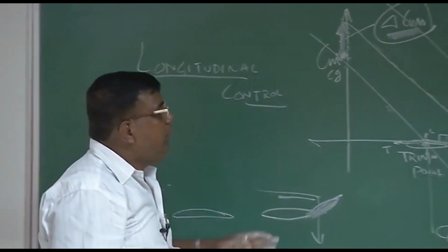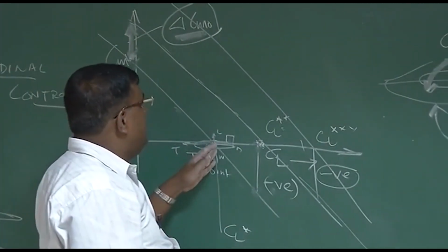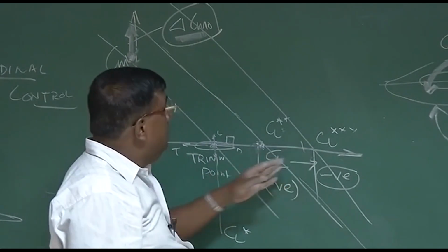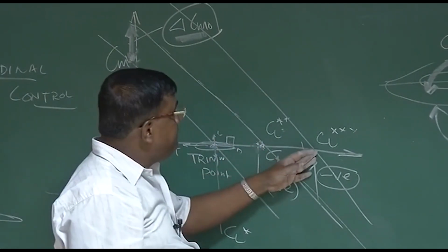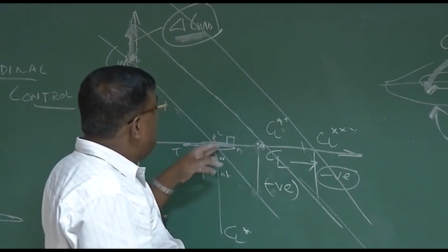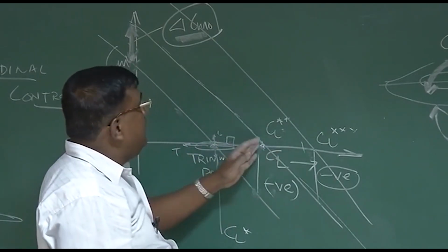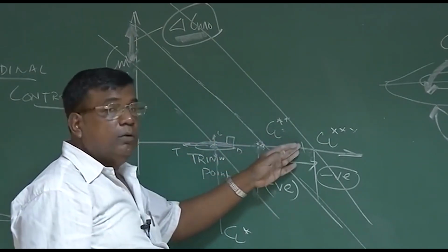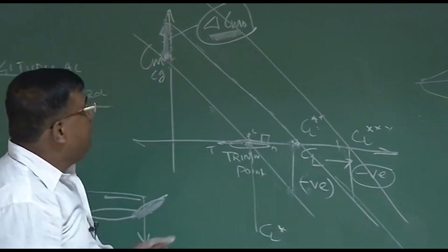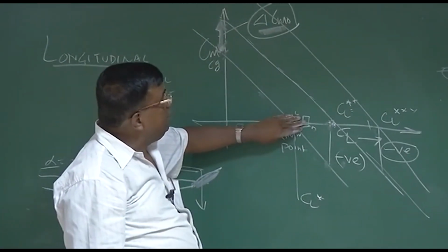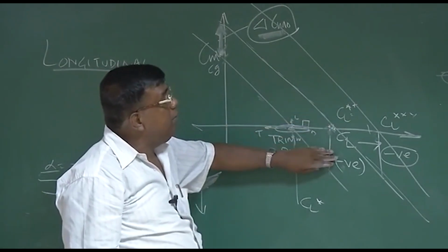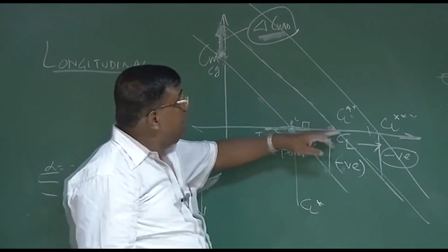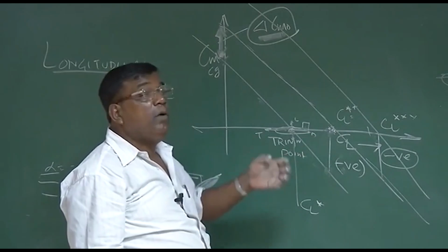This flying at different equilibriums, at different CL here, here, here, this problem we call control problem, and stability part here. So it gives you a connection between stability and control. Okay? Please understand, if I am trying to fly from one equilibrium to another equilibrium, because they are statically stable, they will generate negative opposing moment. To discourage that change, you have to give moment from outside.